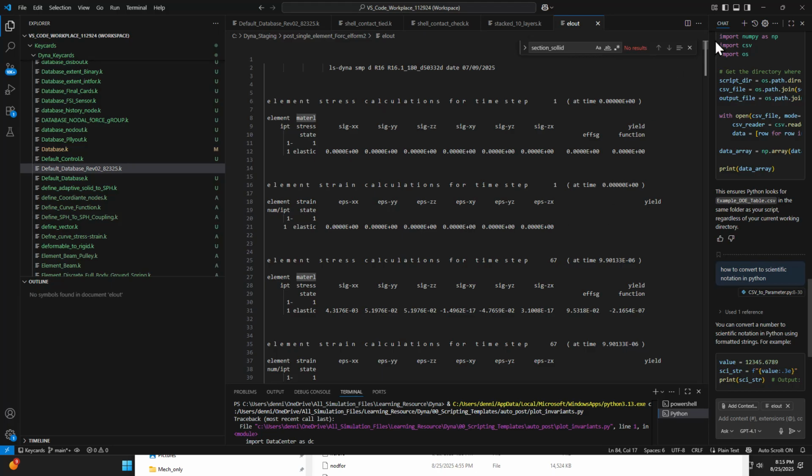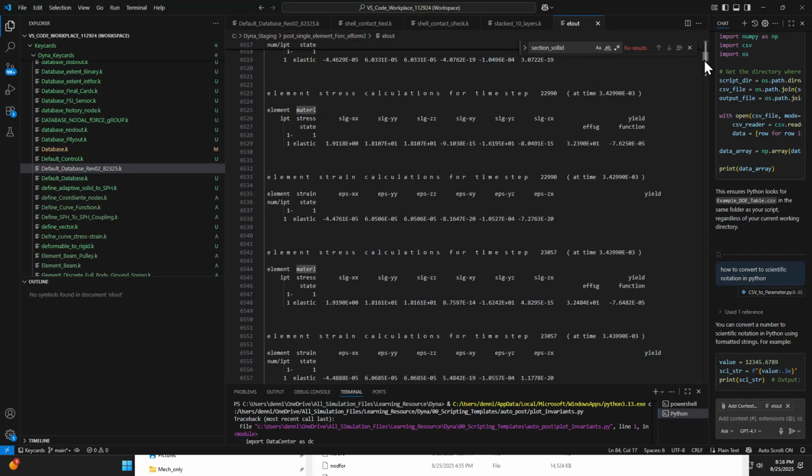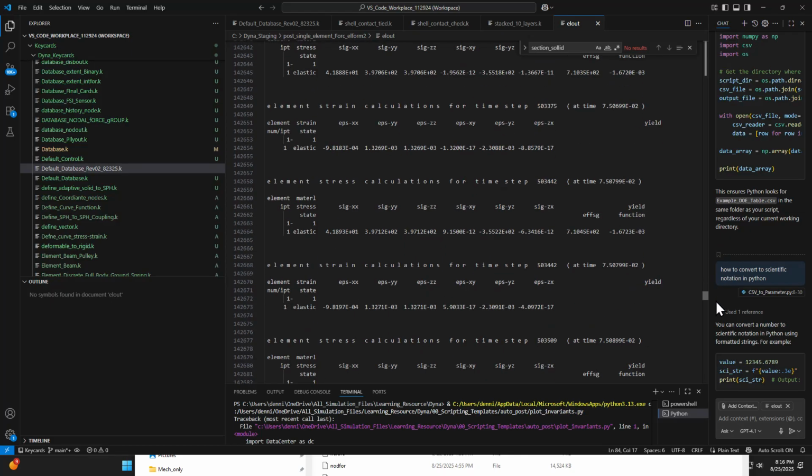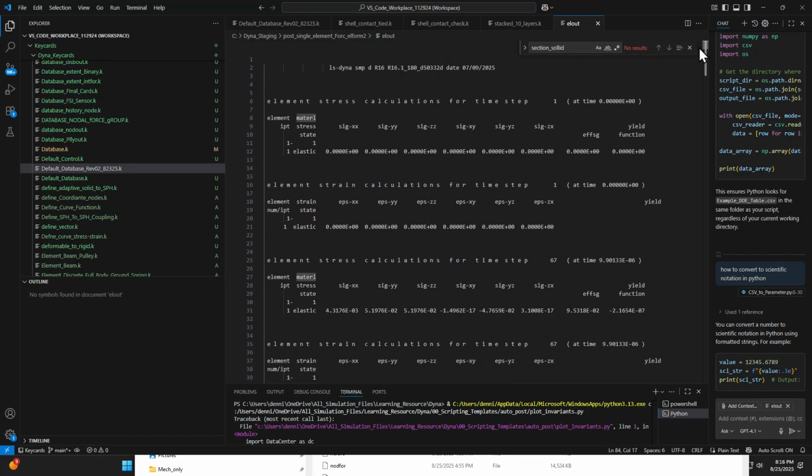In this case, I use the default value of my template, so you actually request a lot. And for each time step, for each state, I can essentially look at each of the elements, and there are 6 different stress components, right? And that allows me to say, for example, if I know my group, I can plot the elements based on their ID, and it gives me a decent look at how this whole thing works, essentially. So you can plot element ID based on element characteristics as a function of distance, as a function of time, and you can plot it for these different stress components.